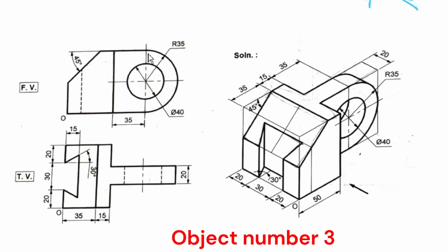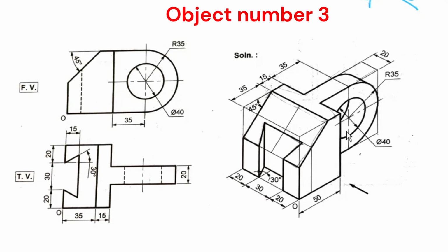This part you can draw. Okay, this is a semicircular part starting from here to here, and then these are the straight lines, and then there is a circle in this. But this you will not draw on the extreme left face, that is the face towards the observer, but you will go inside by what distance? By this distance, and then you will draw it here. The only thing is when you are drawing this circle or ellipse, those construction lines will come on this surface also. Okay, it will come on this surface. Okay, so no issue, let the construction line come. Okay, your solution should look like this.